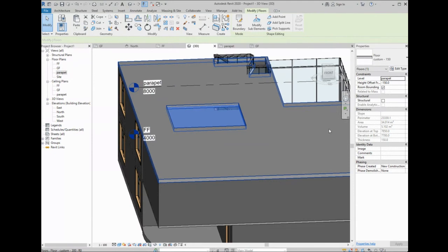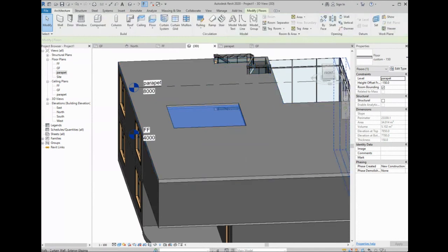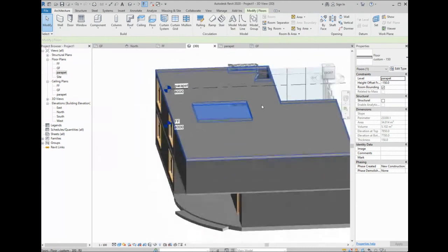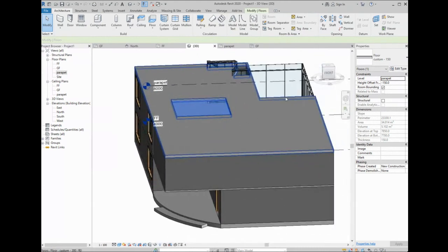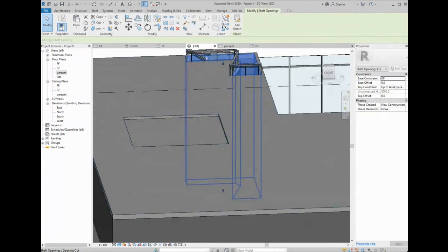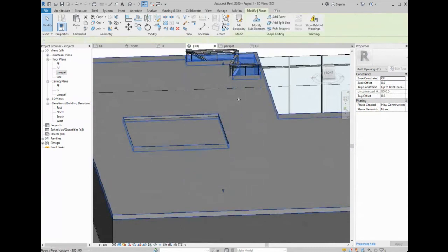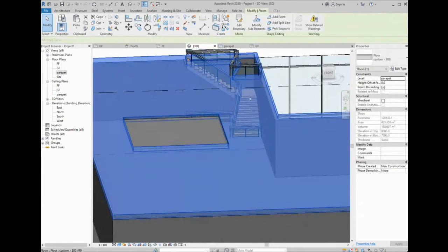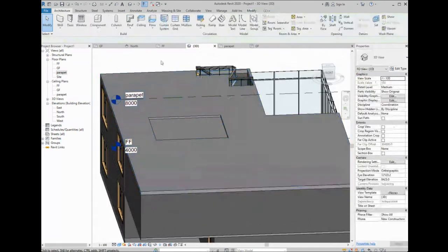Okay. So next we're going to work with masses. Before we go with masses, you have a question? Doctor, regarding the staircase, if it's a regular staircase, for example U shape, for the flooring, cutting the floor with the U shape on the first floor, is that correct? You don't have to create this shape. You can create an opening in the flooring normally, or if you have multiple stories, you can create a shaft. Both ways are correct. At the end, you will reach the same result.